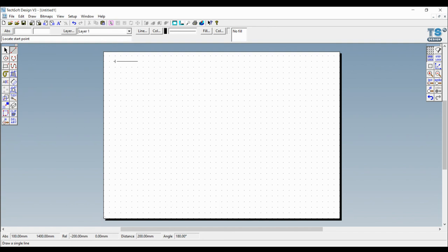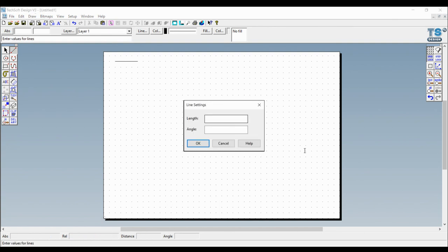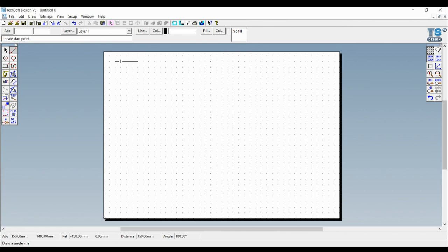So you can very quickly do scaled models in 2D Design. I'll just carry on quickly drawing a 200 by 200mm box. If I make a mistake, I just press escape. So draw out the box that you want, and that is 1:5. Now, if you use the measuring tool, go to the dimension lines here and measure it out like that, it shows up 200mm, the size it needs to be in real life. But actually, it's a 1:5 scale.